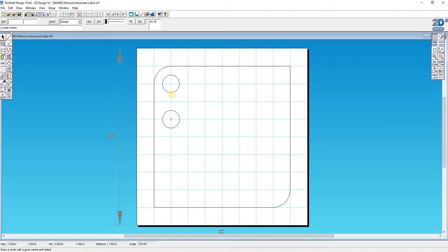That's nice. An alternate way that I can do this, if you want to, is I can go back to the circle tool, and rather than working with grid lock, I'm going to go to step lock. And this now means that as I move my mouse pointer around, I've actually got millimeter by millimeter control. So if I come down to the origin here, remember these squares, the blue squares, the grid is 1/2 centimeter grid.